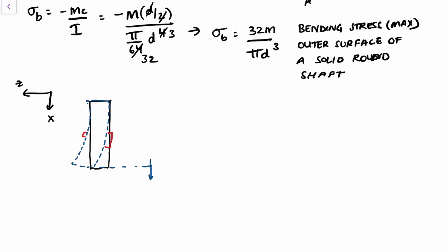Conventionally, anti-clockwise is considered positive when y is pointing out, but this is rotating clockwise. So Fx is causing a moment about y, which is negative.